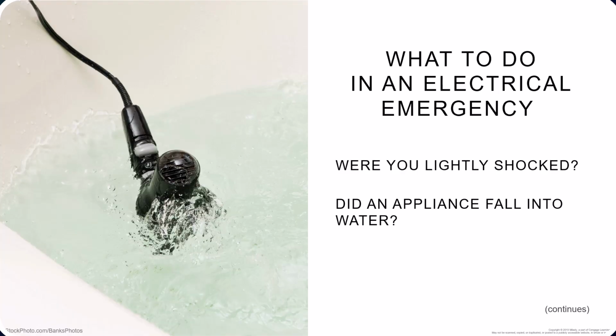If you drop an electrical appliance in the water, so you got a bath bomb or something, electrical bath bomb, if the outlet is GFI protected, it should kill the circuit immediately, and you may unplug the appliance from the wall after releasing the appliance. Do not have one hand in the water and one on the outlet. If the outlet is still live, your body could conduct the electricity.